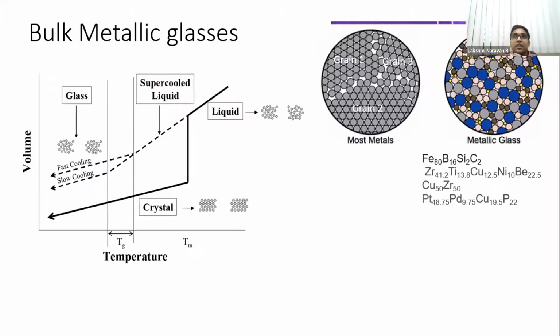That's very nice, because the amorphous nature of the material remains there for a longer period, and then you just need to quench it over a shorter range of temperature, which is much easier. If you have to quench from 1000 degrees to 10 degrees in 2 seconds, it is much harder than quenching from 200 degrees to 10 degrees in the same amount of time, right?